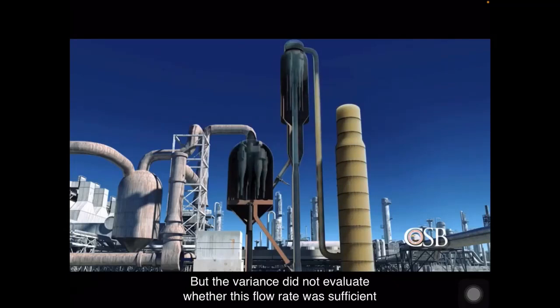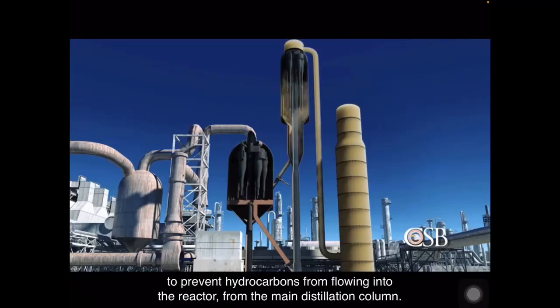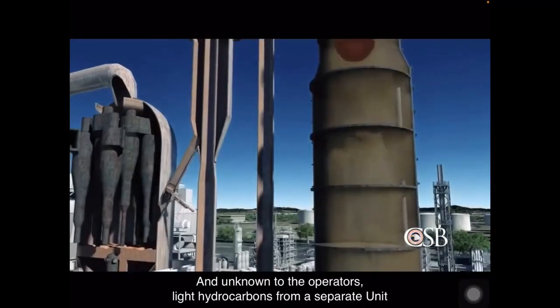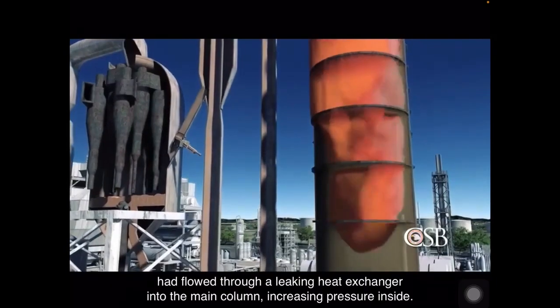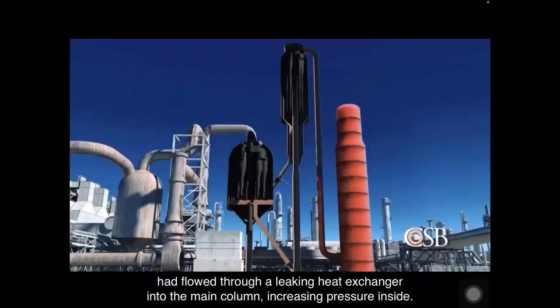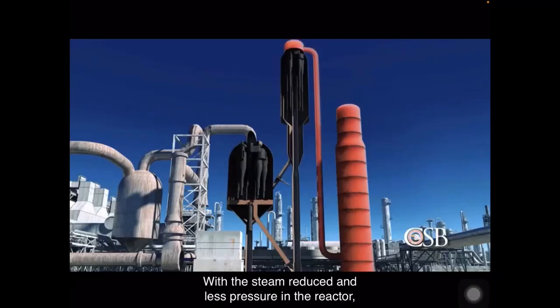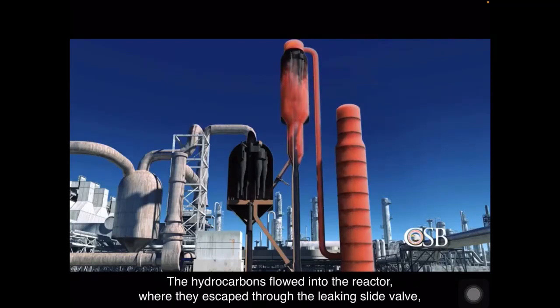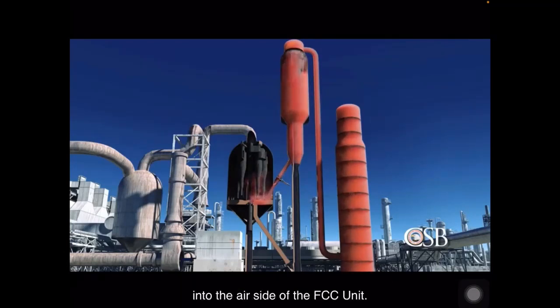But the variance did not evaluate whether this flow rate was sufficient to prevent hydrocarbons from flowing into the reactor from the main distillation column. And unknown to the operators, light hydrocarbons from a separate unit had flowed through a leaking heat exchanger into the main column, increasing pressure inside. With the flow of steam reduced and less pressure in the reactor, nothing could prevent the hydrocarbons from flowing back from the main distillation column.